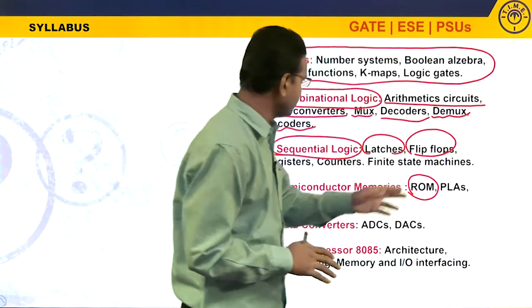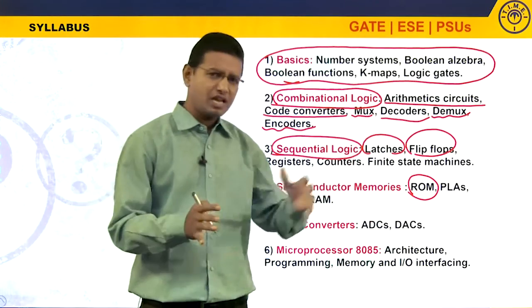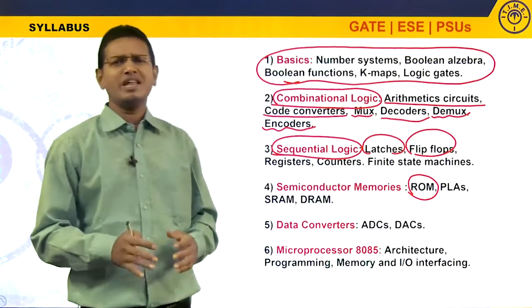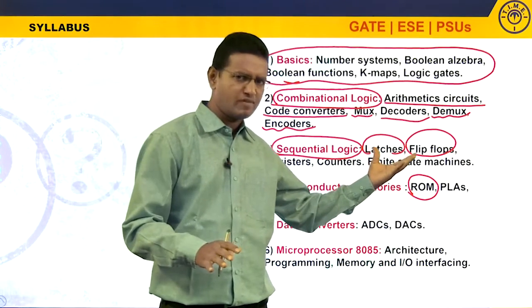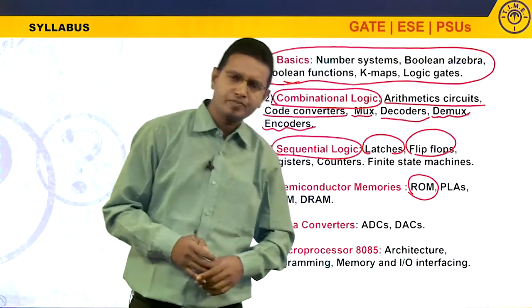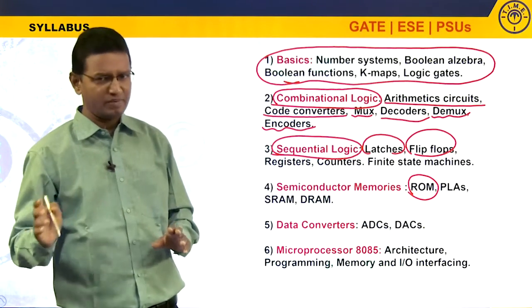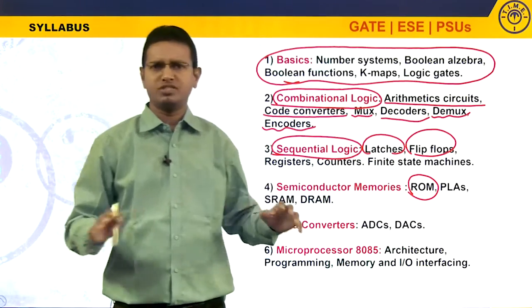And coming to flip-flops. What is the difference between a latch and a flip-flop? First I'll tell what the similarities are. Both are 1-bit memory elements, both have the capacity of storing 1 bit, both are bistable multivibrators, and their basic constructions are the same.